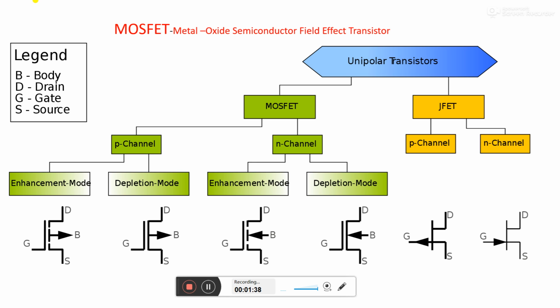If you keep a constant voltage across the drain and source and we further increase the reverse bias across the gate, then the depletion layer across the gate will go on increasing, and at a certain voltage level it reaches the maximum, pinch off. That is, on either side the depletion layer goes on increasing and no current flows in this condition. That voltage is called the pinch off voltage.